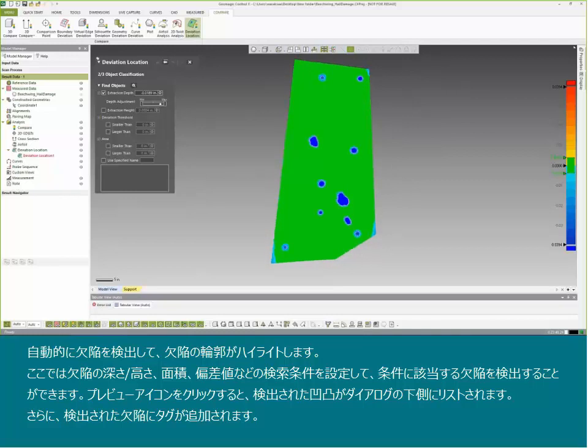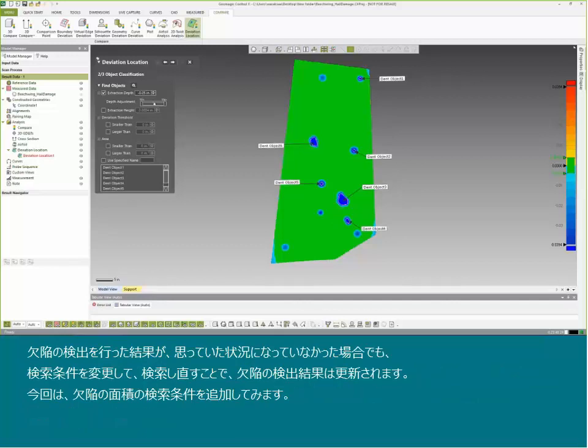Right now we're saying that everything that's basically 20 thou or deeper is being outlined. Maybe we want to increase that a little bit more, to something a little more reasonable. We'll do something like 50 thou, and see if anything's further down than that, that'll be our things of interest. You see automatically it got rid of a couple things that were very shallow on the surface here. It highlighted everything else and gave them a nice little tag, just to let us know what it's doing.